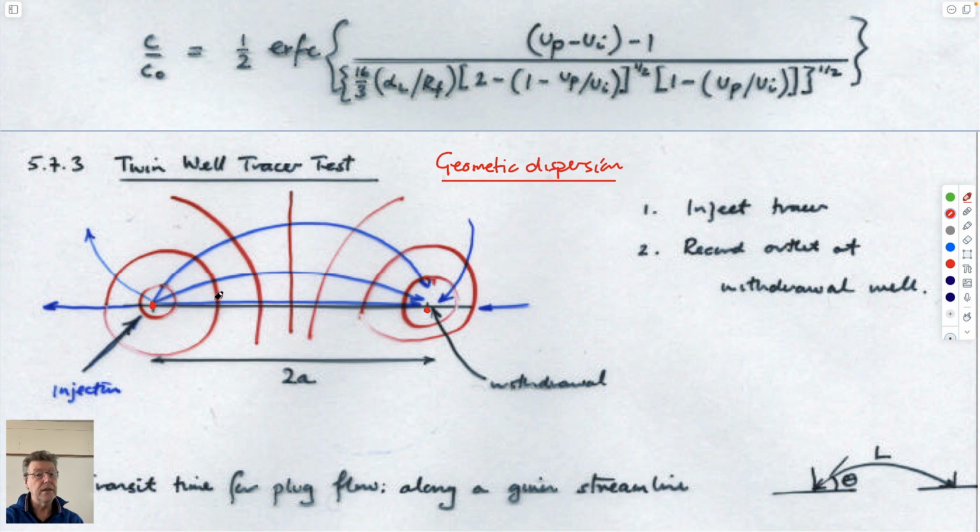You know how to get the volumetric flow rates through this, right? Through flow nets. So you could calculate the volumetric flow rate in this is equal to number of flow channels divided by the number of drops multiplied by hydraulic conductivity times the head drop, if you remember that. So the number of flow channels is 1, 2, 3, 4, 5, 6, 7, 8.